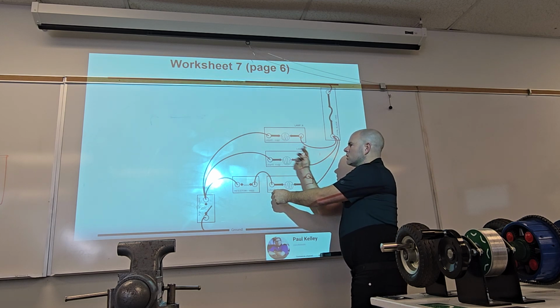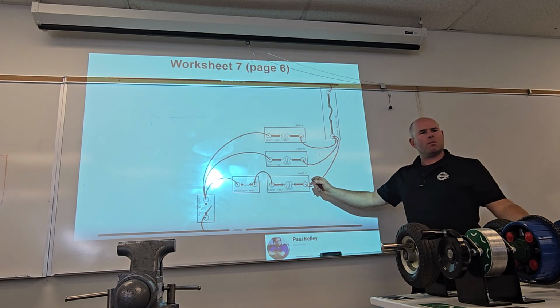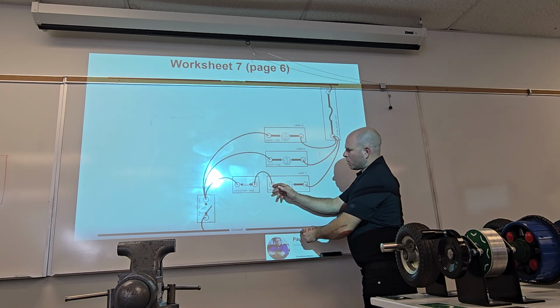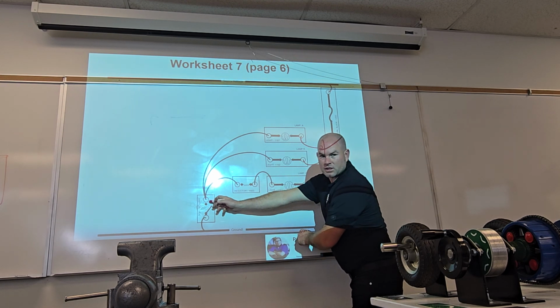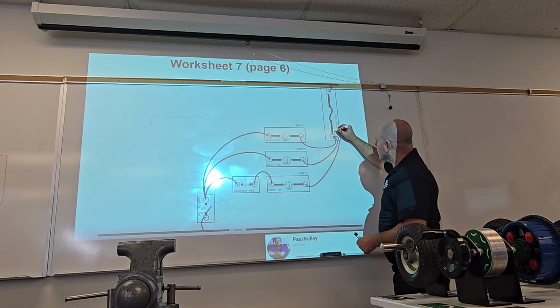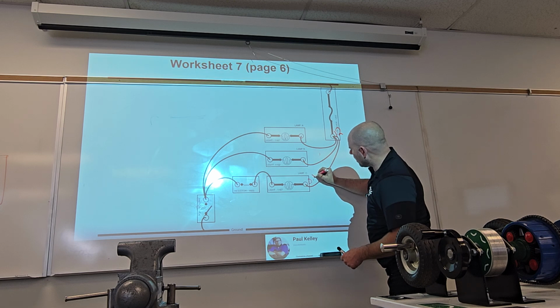So you know this circuit's good, you know this circuit's good. It's dropping 0.1, and then you might need to switch to available to have it make more sense. Then you'd be like, let me do available. 12 volts, 11.9. That tells you the problem's down here. What if it was a different way? What if I got this? 12, 0.1.